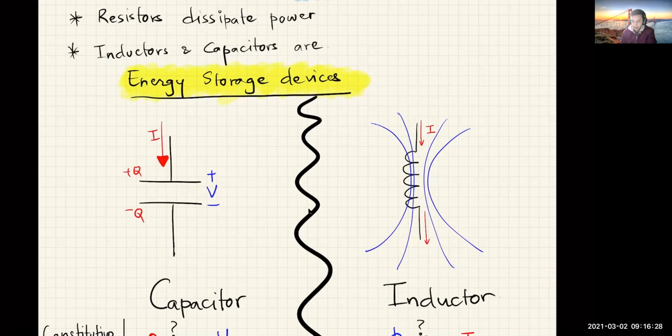But still, what can happen is as you run the current through it, you will generate some magnetic flux around it. And due to the changing magnetic flux, you will create some finite voltage across it, right? So there will be some finite voltage created between the two ends of the inductor, even though it's just a piece of wire.